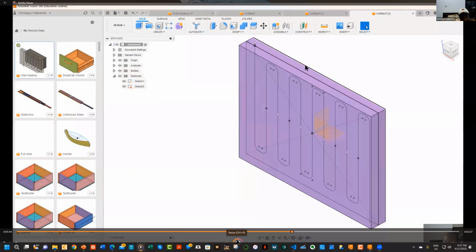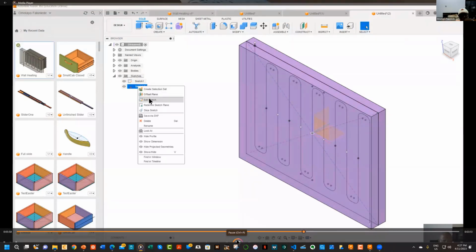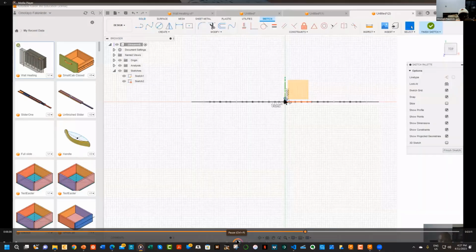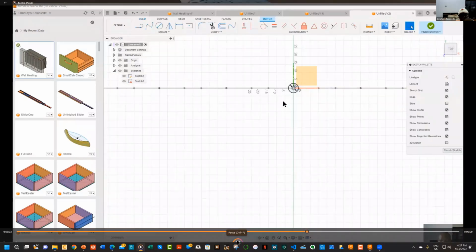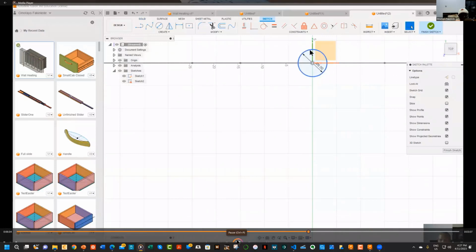The next thing we're going to do is place a hollow pipe, using maybe copper, inside that hole. To do that, we go back to edit the second sketch. Edit sketch. In this sketch, remember that our first hole was 6 units.